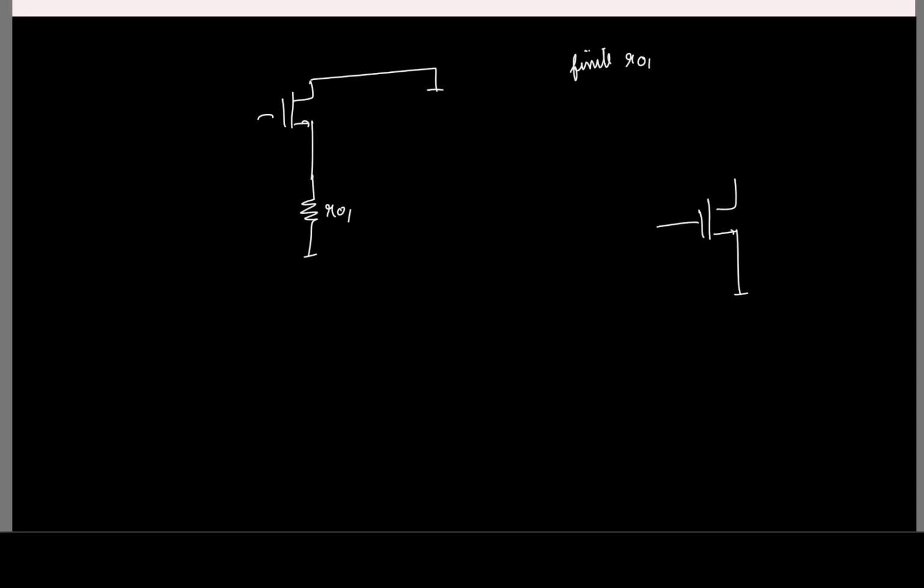Okay, we can look carefully. So MOSFET, let's say I include R0 for the MOSFET. Okay, and I know that the noise in the MOSFET can always be modeled like this. This is the fundamental model. Okay, so now if I try to find the input referred noise voltage for this guy, I'll be shorting the input, short the output. What will be the current flowing? So I out will be IN.